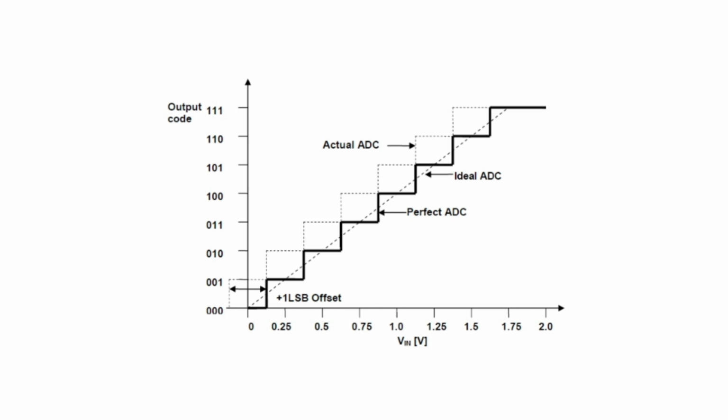Sometimes, a sensor could provide us with a voltage measurement image of the physical value with an offset voltage. This voltage could be corrected by software if it is not corrected using circuitry before feeding this signal to the ADC channel.